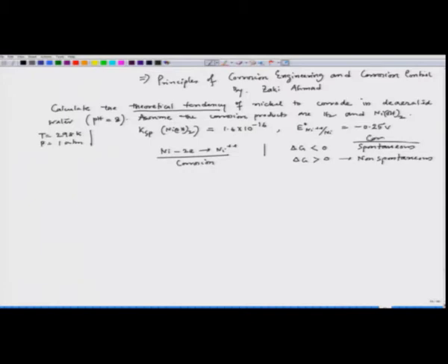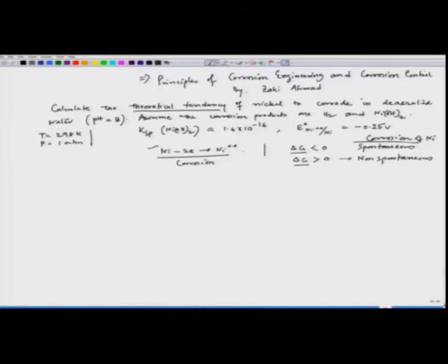We are talking about corrosion of nickel. Now, when we say the entire system, so not for this particular reaction, we have to see the another reaction which takes place, because this is my anodic reaction. So, we have to have a cathodic reaction. So, cathodic reaction is this. So, now if I add them, then it becomes Ni plus 2H plus goes to Ni plus plus H2. So, this is my overall system reaction. That means, there is an equivalent cathodic as well as anodic reaction.